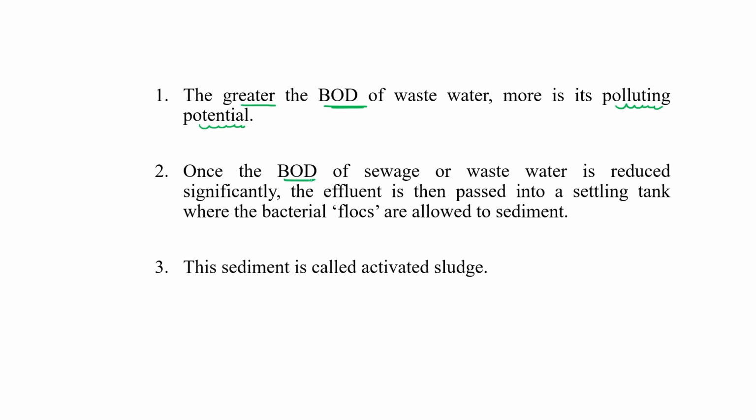If BOD is reduced, then we can say it is now treated. Once the BOD of sewage or wastewater is reduced significantly, the effluent is passed into the settling tank, where bacterial flocs are allowed to sediment. This sediment is called activated sludge after treating in the aeration tank.